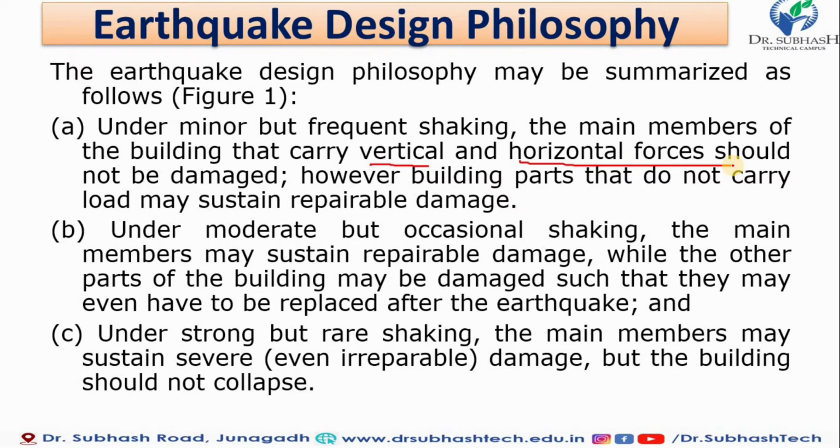with new ones. And the third point: under strong but rare shaking, the main member may sustain severe damage. Even replacement should be done after the damage, but the building should not collapse. So under these 3 criteria, our design philosophy applies while the building should be designed as an earthquake resisting building.